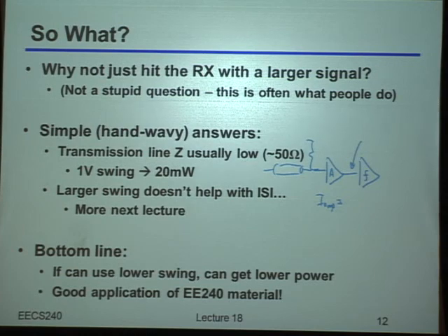That's correct, but I actually want it in terms of things that you know. So let's say that I tell you I want a certain gain and I want a certain bandwidth. There we go. Exactly. So it's just the gain times the bandwidth times V star times the load capacitance.